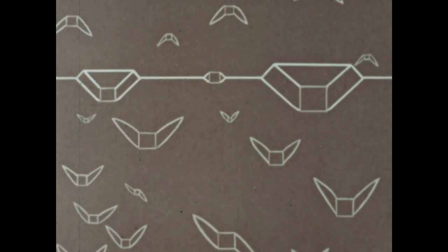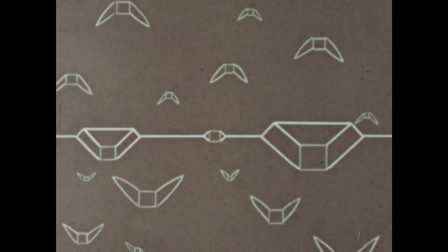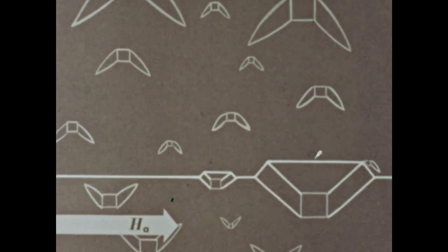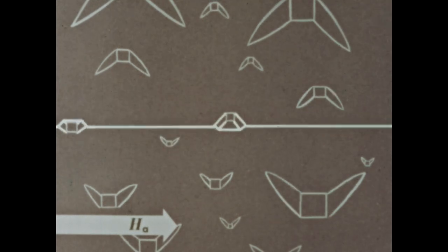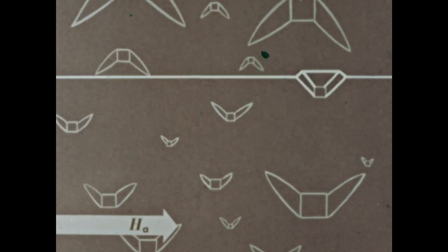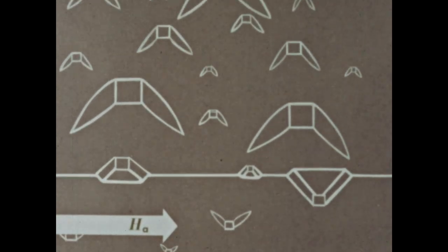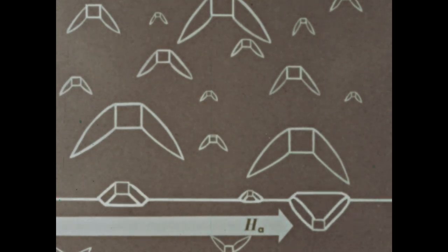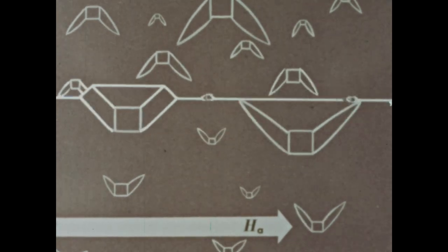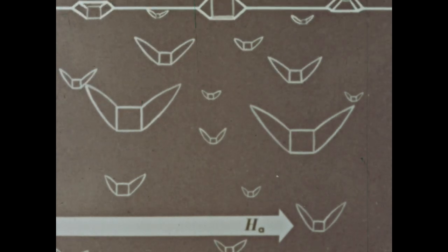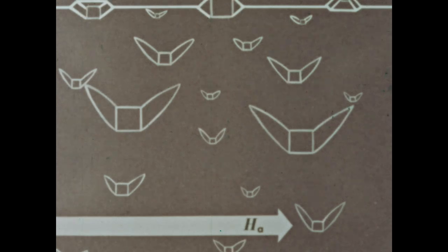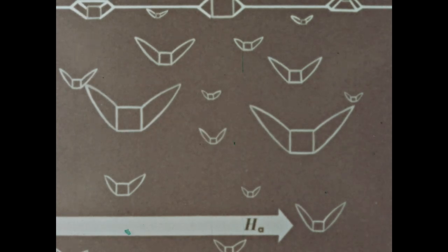In most cases, the distribution and size of inhomogeneities will be somewhat uneven. This causes the impedance to motion to vary with the wall position. When a substantial impedance is encountered, a large field is required to overcome it. Then, after the primary wall breaks loose, the field may send the wall shooting forward rapidly until another large impedance is met. Such jumps cause Barkhausen noise.